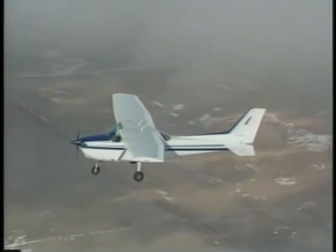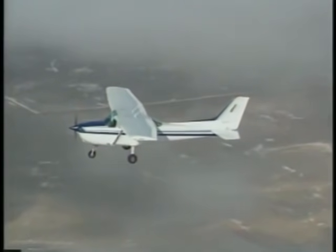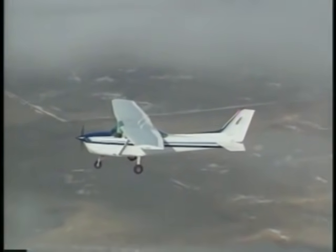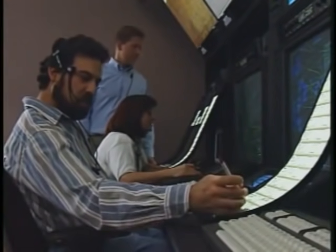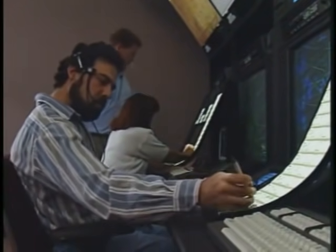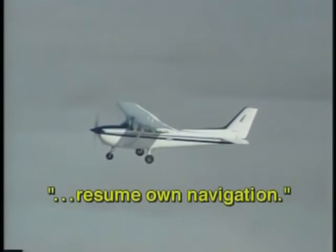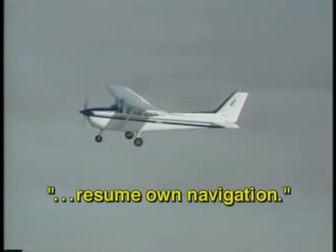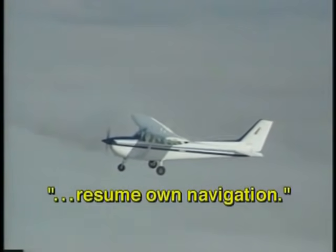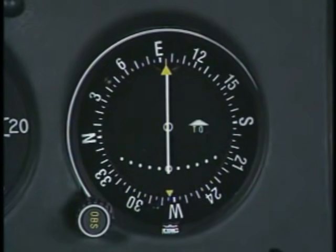However, it is your responsibility to maintain adequate obstacle clearance until the controller issues you a vector or other instructions. Departure control will then give you specific headings to fly in order to intercept your clearance route. Once the final vector has been given, the controller will tell you to resume own navigation. This phrase means that the controller now expects you to navigate using your own equipment. It does not mean that your flight is no longer in radar contact.